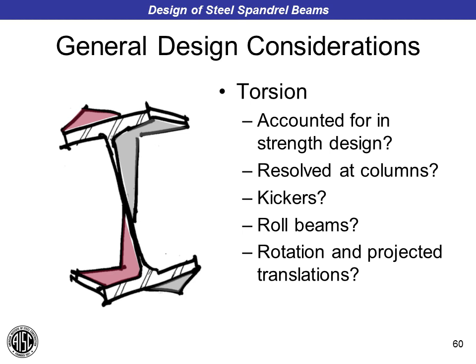One is for what AISC Design Guide 9 Figure 3.3 calls a rigid support, which not only resists the twist at the end, but also has warping normal stresses associated with it. Or you have what Design Guide 9 calls a torsionally pinned connection to the column, which has torsional shearing stresses greater than 0 but has no warping normal stresses associated with it.